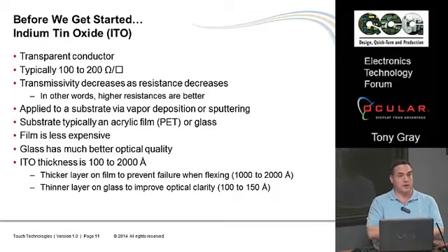The way it works is you put it down on a sheet, some kind of substrate, and when you put it down as a solid, you get a resistance in ohms per square, which, if you think about the math and how it works out, seems kind of strange at first if you've never gone through it. But the way it works is you model it as a series of resistors that are all in parallel as well as in series with each other.